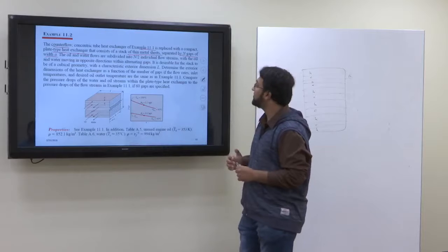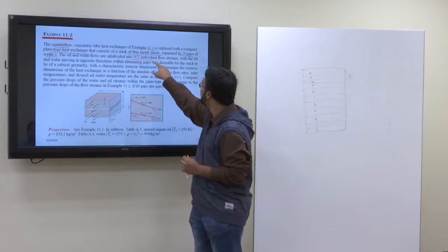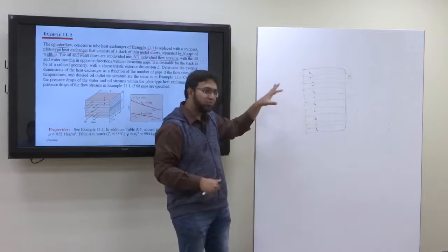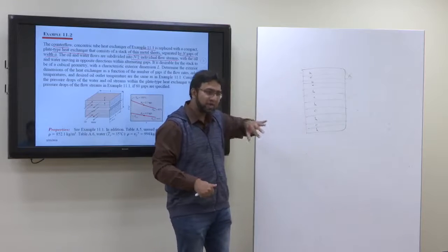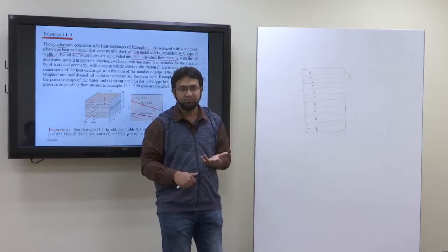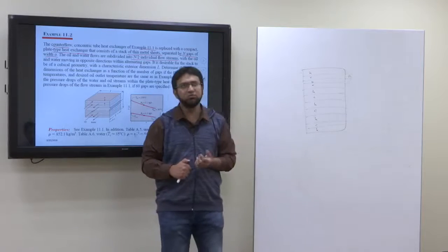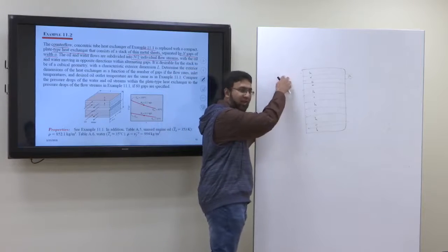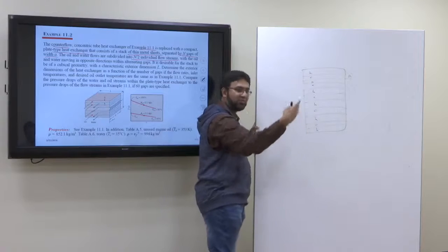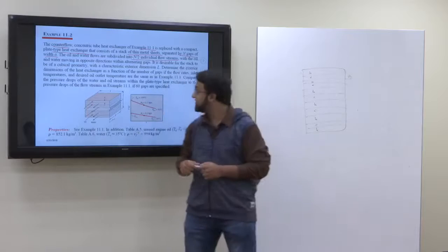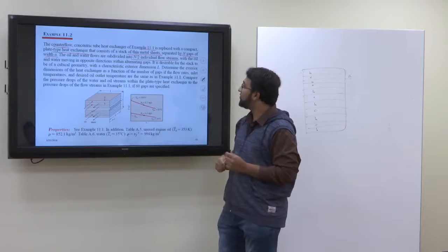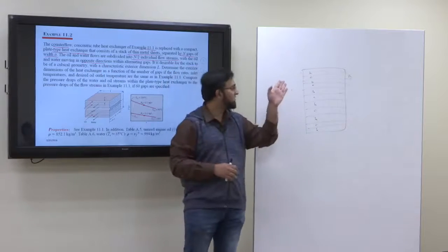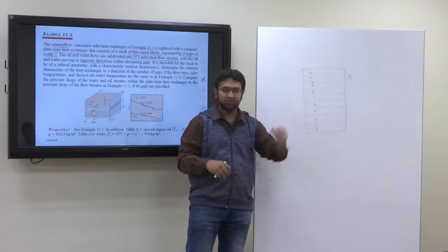The oil and water flows are subdivided into n/2 individual flow streams. Obviously, if we have n gaps, then n/2 gaps will be with the hot fluid and n/2 gaps will be with the cold fluid. If we have 100 gaps, then 50 gaps will have hot fluid in them, and 50 gaps will have cold fluid in them. With the oil and water moving in the opposite direction, so it's again counterflow. Let's say oil is moving inside, so water is moving outside.